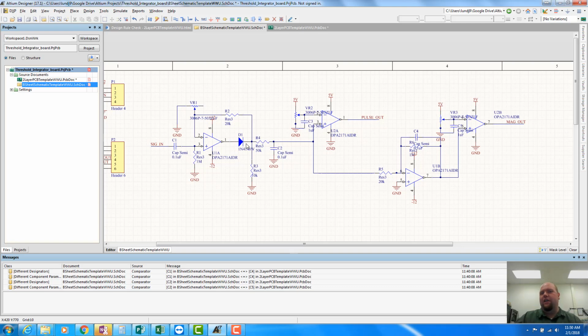They're all going to have numberings that are related to each other, and it's just going to make it easier to connect these different annotated parts to where they are logically in the circuit. There are not a lot of components over here, but you can see that if the component flow is left to right, then typically we want our annotation to be from left to right also. So that's one thing we did.